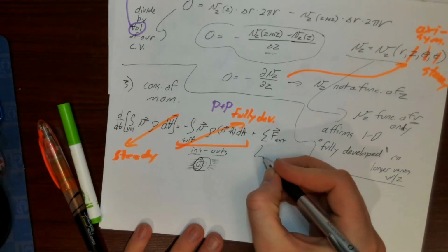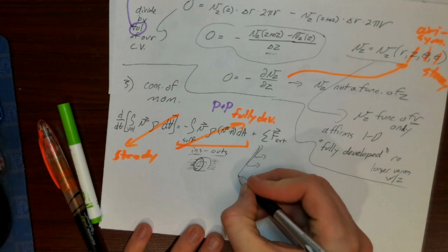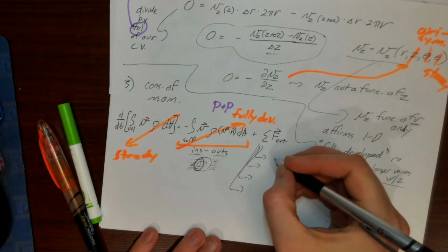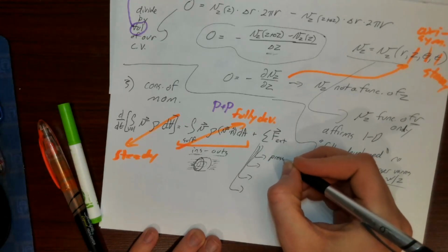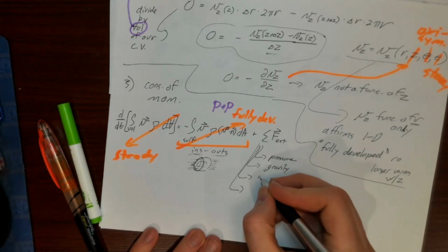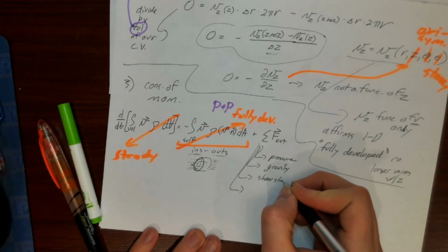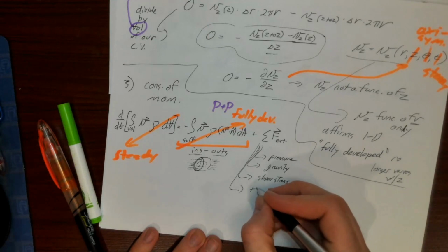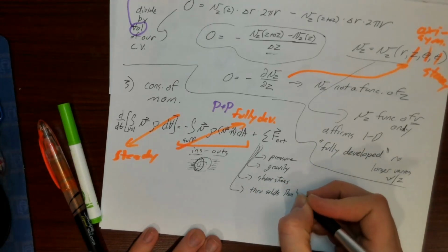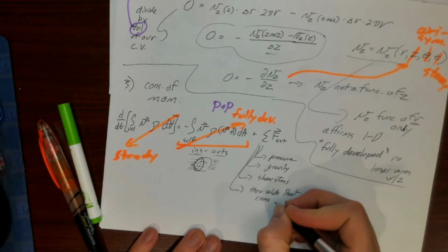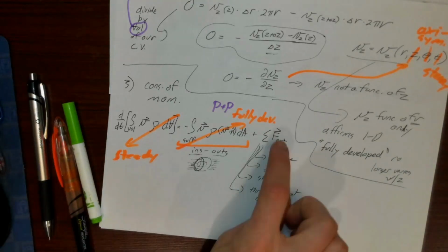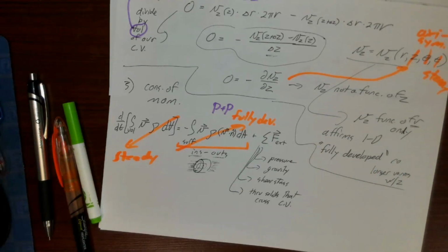We said external forces come in 4 flavors for fluid problems with control volumes: pressure, gravity, shear stress, and forces through solids that cross the control volume. Can we cross any of these 4 flavors of force out from the beginning?